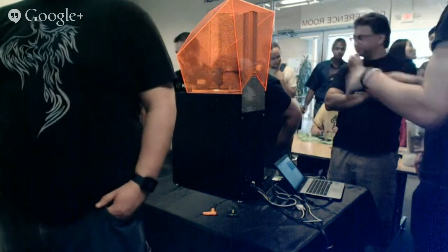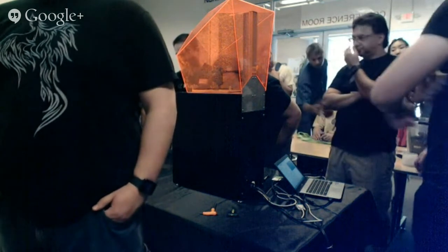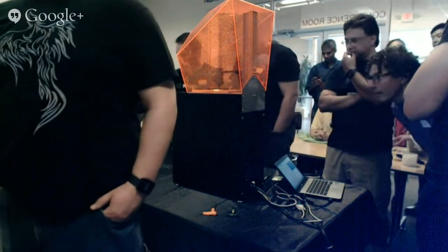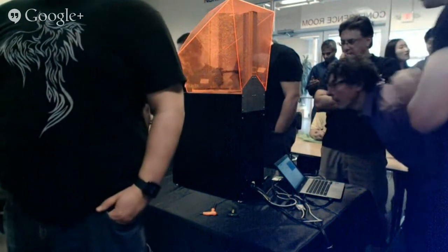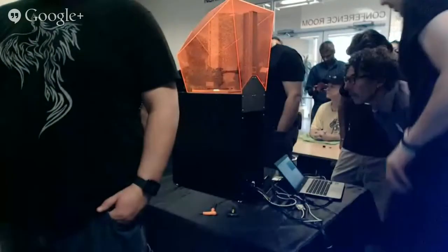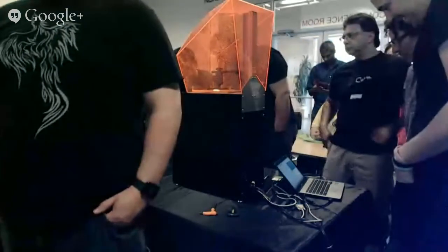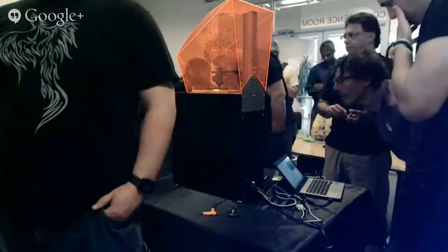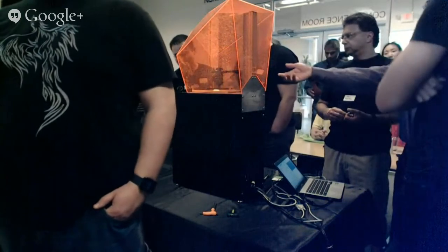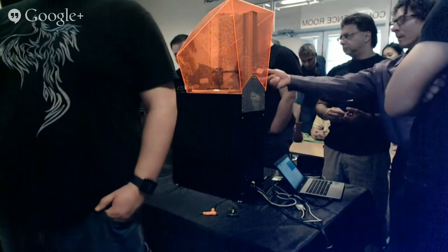Not to get rid of the resin, but because there is pigment in the resin. And over time, the pigment will stick to the side. It's hard to get off. And I'll use alcohol to get rid of any stuck on pigment, particularly if I'm switching from black to clear. Then I might shoot any specks of leftover black with alcohol. So for ordinary resin cleaning, dish soap is sufficient.